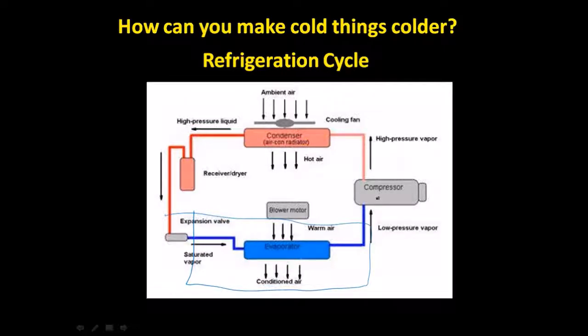It goes into the compressor. The compressor puts it under high pressure, and it takes the heat outside the house again and blows air across it again to cool it off. And so what's happening is, as a cold liquid and vapor, it's removing energy from inside the house. As a high pressure, very hot liquid and vapor, it's putting heat out into the environment as environmental air is blown across it. So it's removing heat from the house without removing air from the house. Pretty cool, huh?